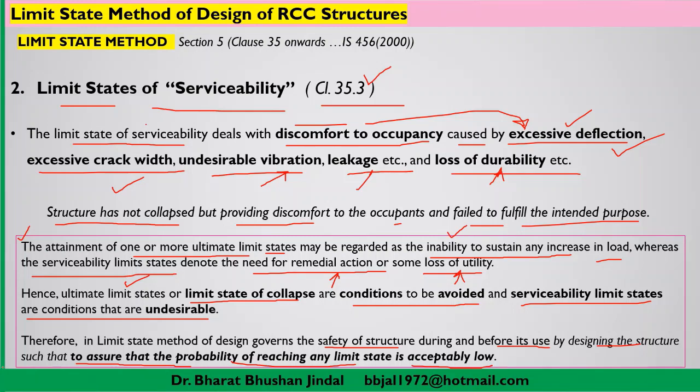So we have to design the structure accordingly. We will be choosing the section, selecting the material, as well as applying various checks. Those checks may be related to strength, deflection, crack width, leakage, durability, etc. All these things we have to take care of while designing any RCC structure with the limit state method. Thank you.